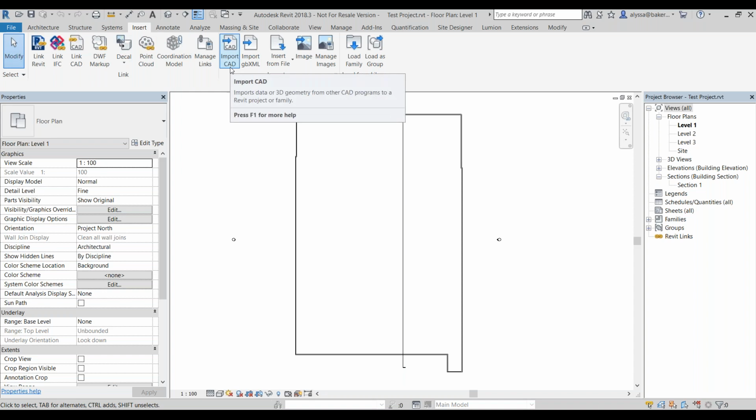With regard to importing the CAD, if you import it in here, it's kind of its own object within this Revit file, and it has no relation thereafter to the external file or the original DWG. So that's the difference between those two. Essentially, if you need to import or link in any kind of CAD, you would use either of those two formats. But what happens when you actually have things like, I came across a company who had a structural engineer who was still modeling his items in AutoCAD, and it was a whole floor slab, and we needed to bring that DWG into Revit.